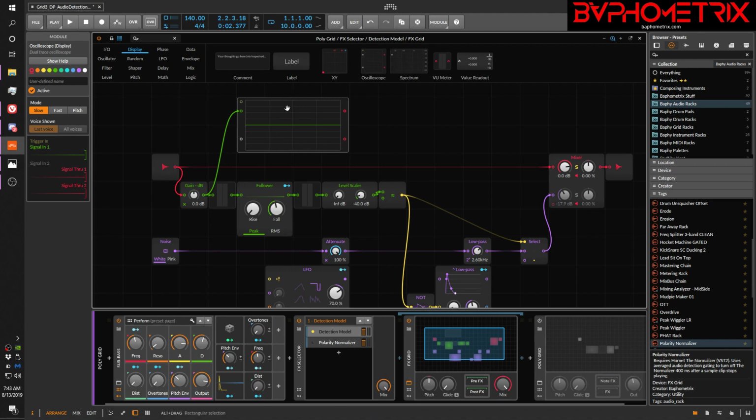So logic gates are a unipolar signal from 0 to 1, and they only trigger true when the unipolar value is above 50%. So when you feed a raw audio signal into something that's trying to detect is there audio or is there not, if you're not doing something special to flip it all positive and keep it pushed up nice and high, your logic gates are going to keep flipping on and off. And so that's really confusing.